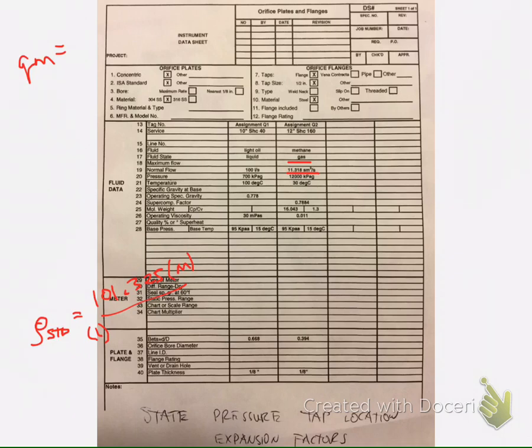This would be at flowing conditions. So if we wanted the density at flowing conditions, which we will need as well, and then we multiply it by 8.315, and then our absolute temperature. Let's just see what our temperature is. It's 30 degrees, so it's going to be 30 plus 273.15 Kelvin.